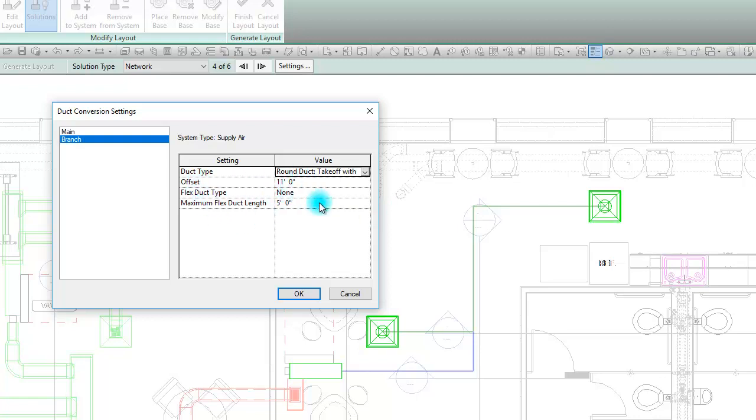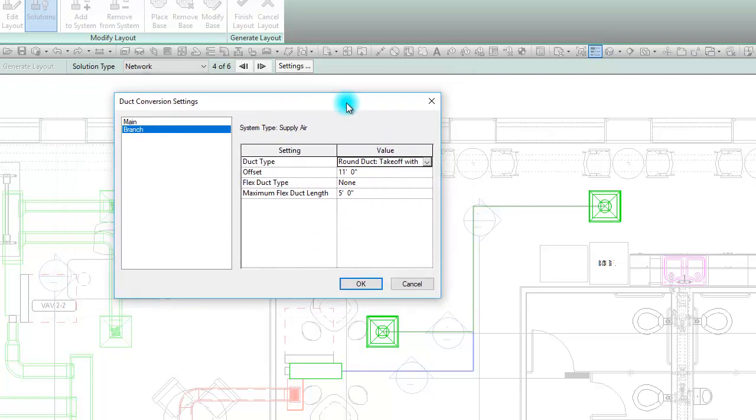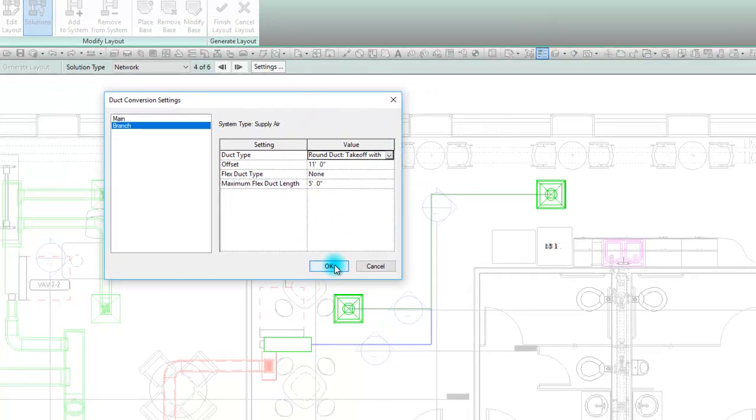I'm not going to allow any flex duct in my model. The contractor on my projects will have to look into the spec for that information. Flex duct has its place, however, I don't model with it because it doesn't flex and update well over time, especially when you start changing elevations. So I've seen some flex duct do some very funky things. So I avoid it. I stick with hard connections, which actually is better for pressure drop. So you can do it however your firm does it.